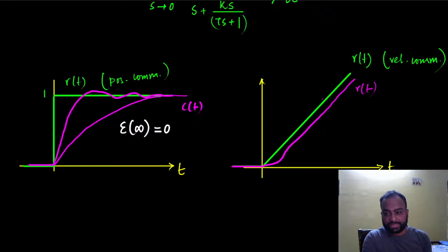Again, it has reached a steady state. The last graph here. For different values of the parameters k and tau, the response could be oscillatory, or could be like that. But the point is, when the output reaches steady state, or when c(t), which is the controlled variable, reaches the steady state, the error must be zero.